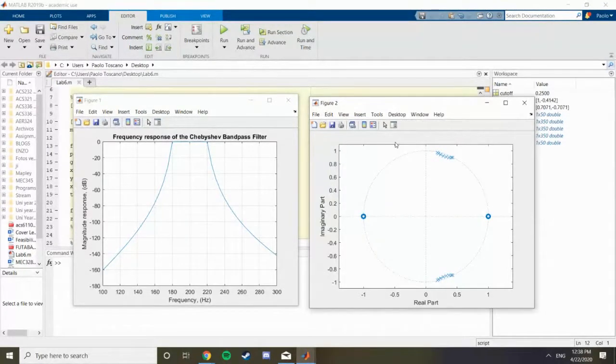We are practicing using the z-plane to design filters this Friday. But the main point is that when we are on the unit circle, when we are close to a zero, we have attenuation in the frequency response. When we get close to poles, we have an increase in the frequency response. Okay, makes sense. Perfect.